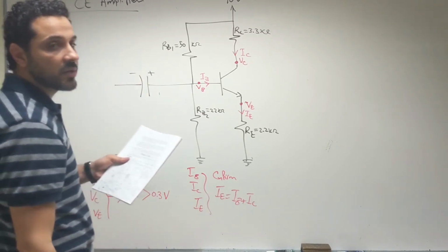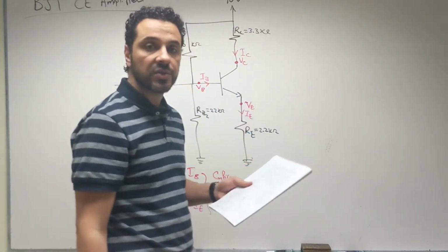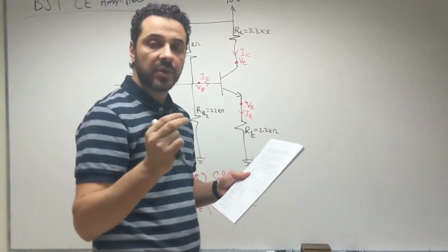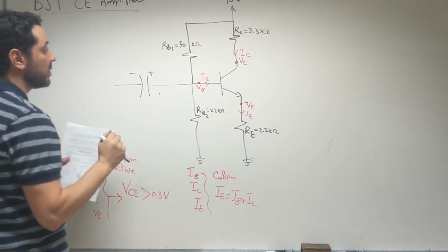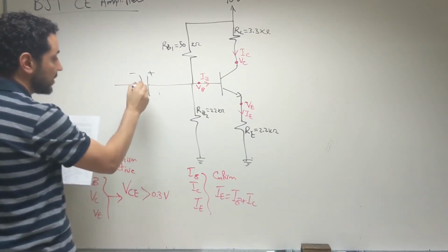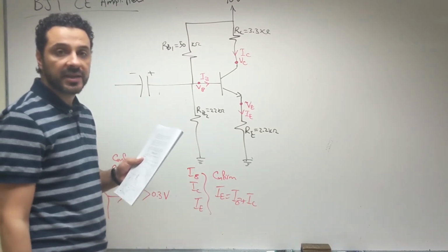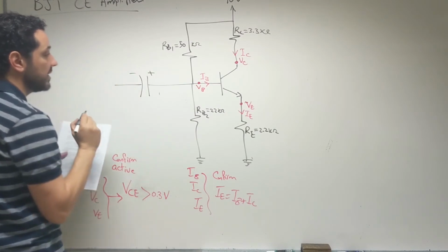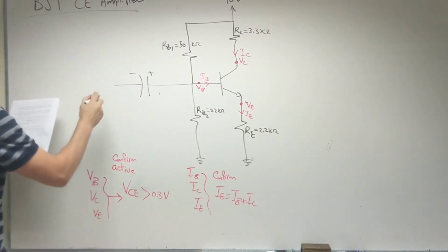The capacitors that we are going to use in this experiment are electrolytic capacitors, which means that the direction of the capacitor is very important. So you have to connect the capacitor in the direction specified in your manual. Please note that for this specific capacitor, it is wrongly marked in the manual. So you have to connect it with the positive on this side and the negative on this side, and please correct it in your manual.